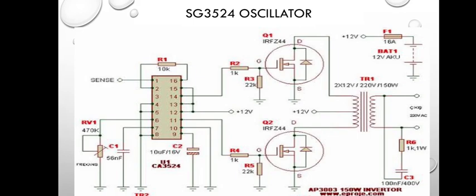That is across pin 6 to ground. You can adjust it to 140k to give you within the range of 50 to 60 hertz. I am very certain of that. I've done the calculation. So a 140k resistor from pin 6 to ground should give you between 50 to 60 hertz. That is the output frequency.